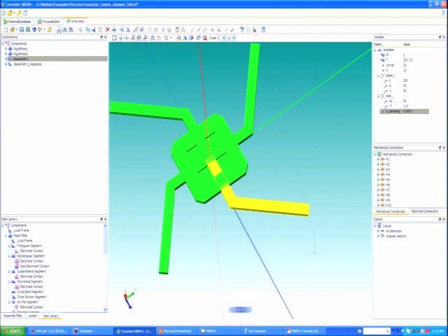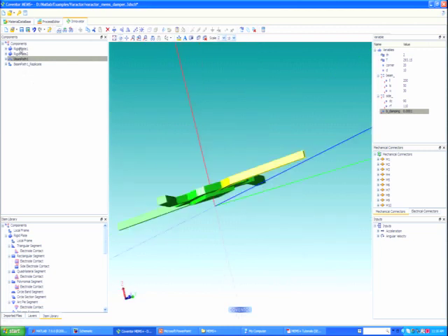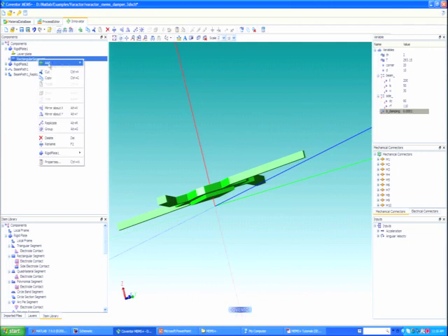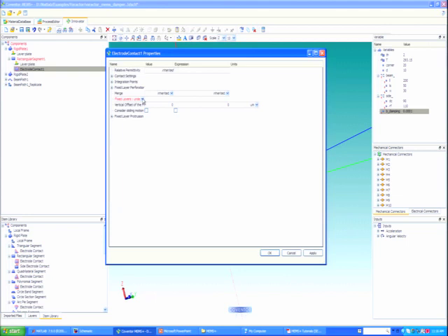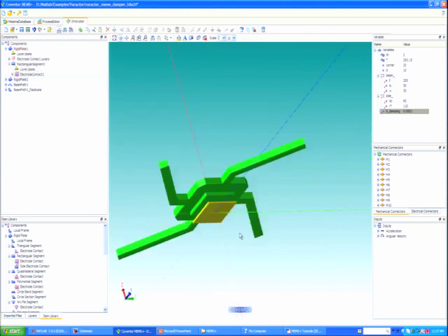Now there are electrodes at the bottom which we can add, and I'll maybe add one just to show you how it's done. Every rigid component comes with its own electrode. So typically for MEMS you have a plate on top, electrode at the bottom. I do right click, add electrode contact. The only thing I need to describe really for the electrode is what layer it sits on, because it inherits, you can see inherited on top over here. It inherits most of the properties from the parent, so things like shape and all that. I just have to say it sits on the electrode layer, and boom, that's my electrode there.